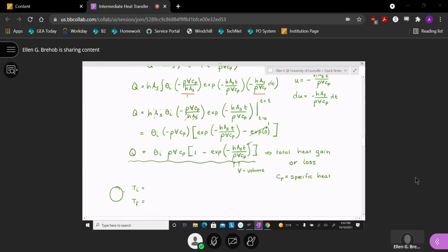If I had to find the total amount of heat loss, because there's no variation spatially, I can solve for the total amount of heat loss by rho volume C sub P, T final minus T initial. Okay. So I think there's times when this equation is like overkill. It's useful for some stuff we're heading towards, but a little bit overkill for this zero-dimensional transient conduction.